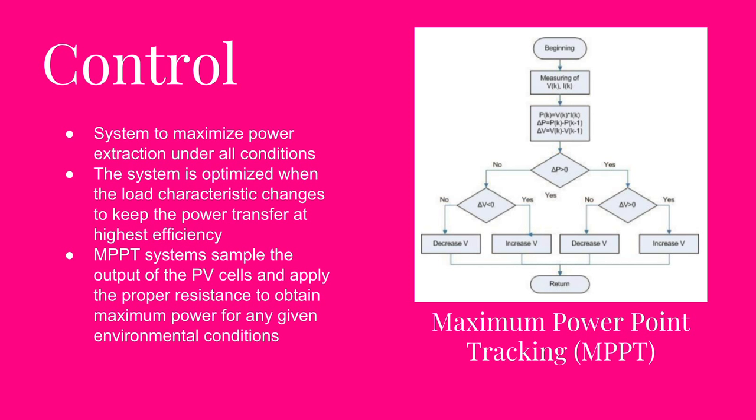This load characteristic is called the maximum power point, and MPPT is the process of finding this point and keeping the load characteristic there. MPPT devices are typically integrated into an electric power converter system that provides voltage or current conversion, filtering, and regulation for driving various loads, including power grids, batteries, or motors.